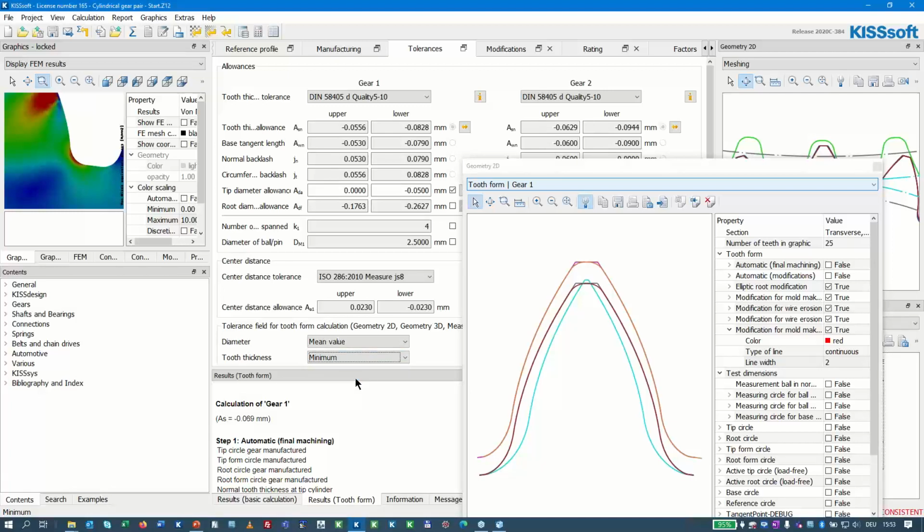because when you produce a lot of plastic gears, the cavity will expand, it will wear. This means as time goes on, the gears that you manufacture by injection molding, their tooth thickness increases and increases and increases because the cavity experiences wear. This means that for the geometry of the tooth that you use, we recommend go for the minimum tooth thickness.